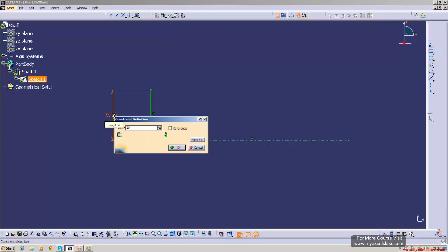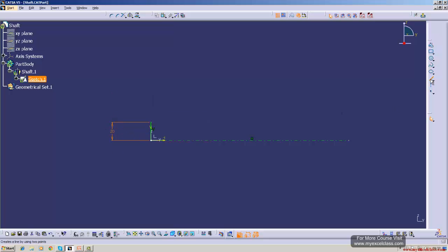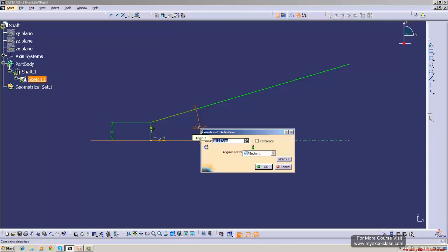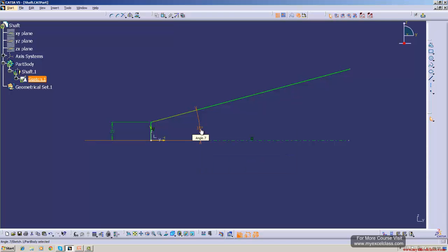Let's say this is 20 mm length. And from here we draw another length. It may be anything, it may be longer also. Not necessarily it should be this up to here, it may be any length. And angle we can assign. See, I will call it as, see now it is constrained because I have selected this. The geometrical constraint is as constraint.